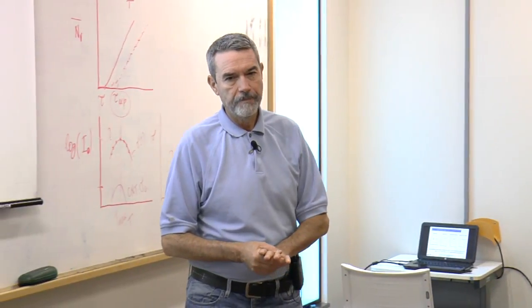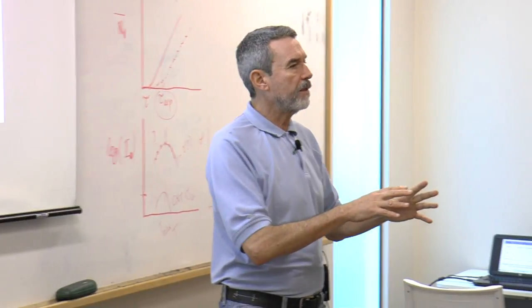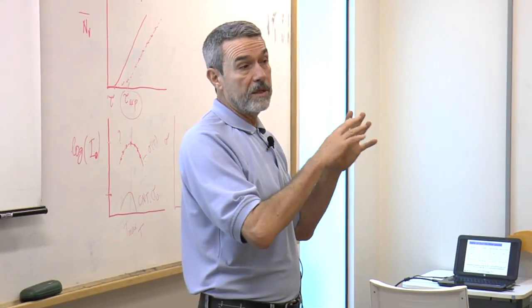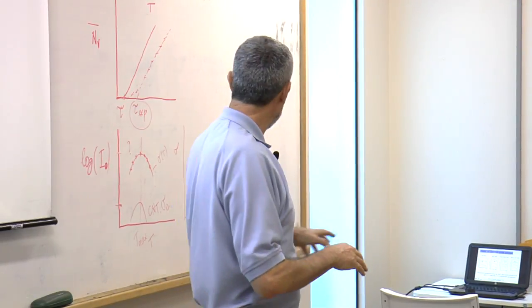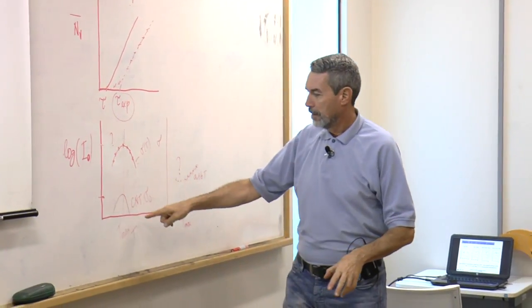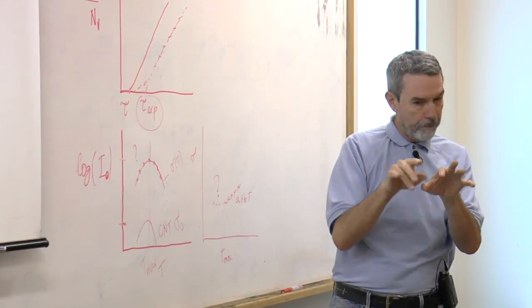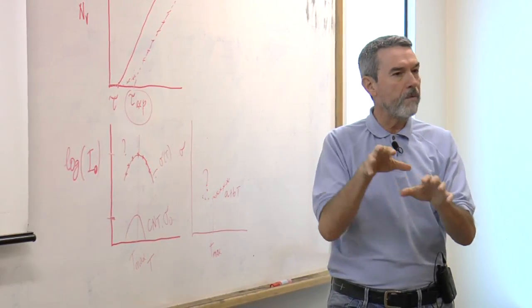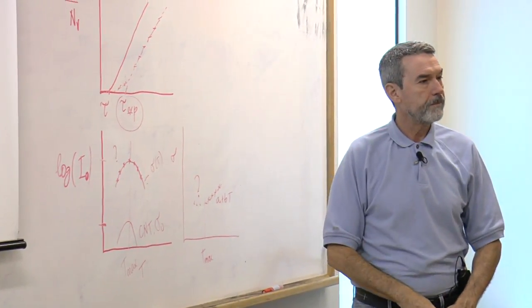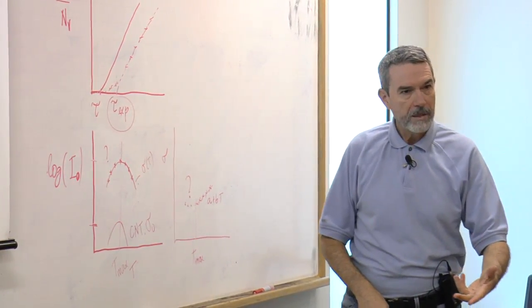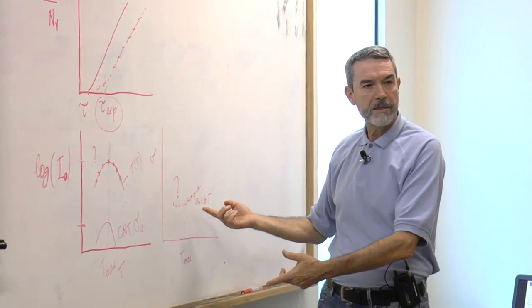Final story, because this is a complex subject. Classical nucleation theory with a constant value of sigma and viscosity can predict the temperature dependence. It predicts the maximum. You can plug in viscosity, delta G, and predict the maximum, but you cannot predict the magnitude. Now we can force fit with a size dependence or with a temperature dependence.